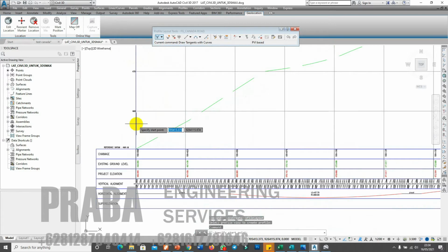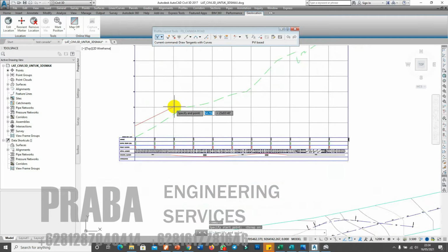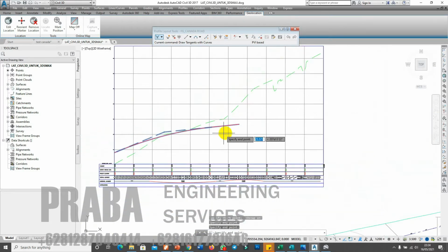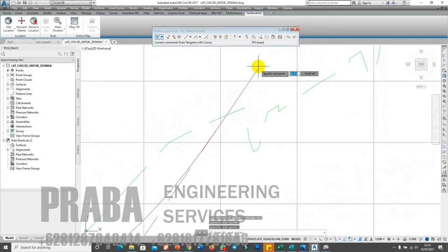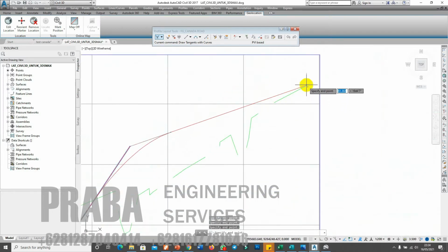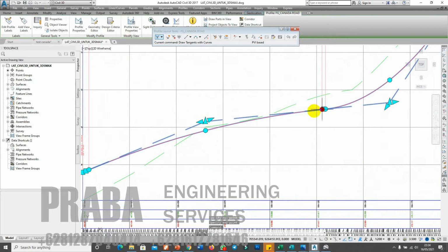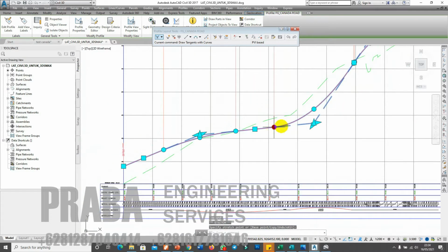If you start from the top of the original ground level, it means it will be embankment in here. If you go under this original line, it means it will become excavation in here. For the practice, it's okay. You can adjust by your own style. But in reality, you cannot do it like this. You need to follow the guidance from the work specification.